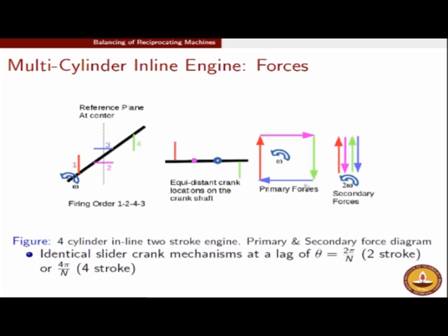We know that finally the total force has to be resolved along the x direction, which is the direction of the slider motion. The slider motion for all these four sliders is the same, which is denoted as x. So at this stage we are just taking the sum total of the rotary unbalances associated with each of the cranks without worrying about taking the components.